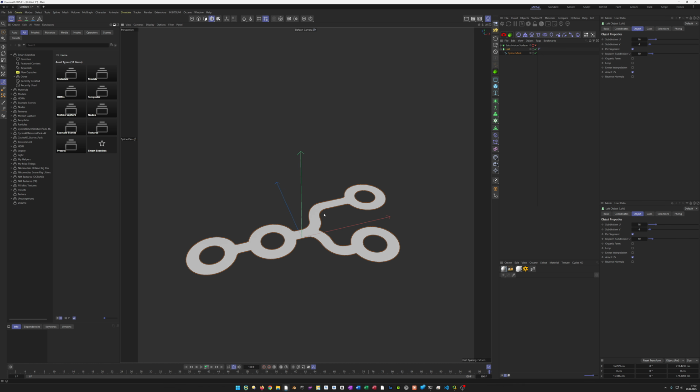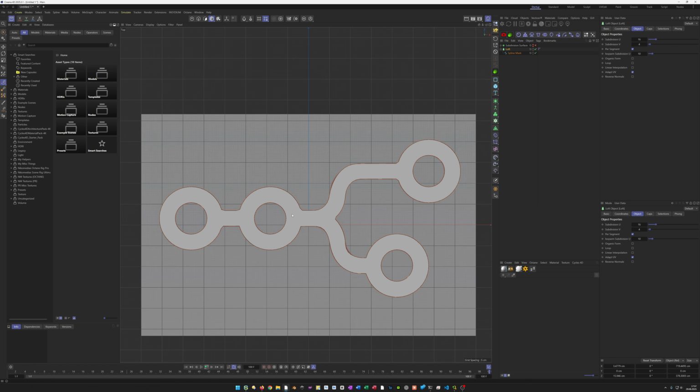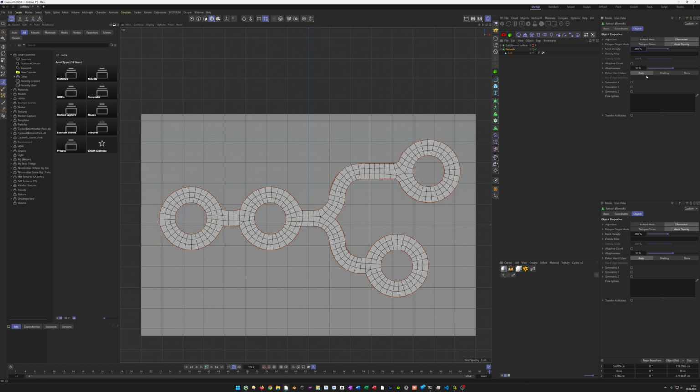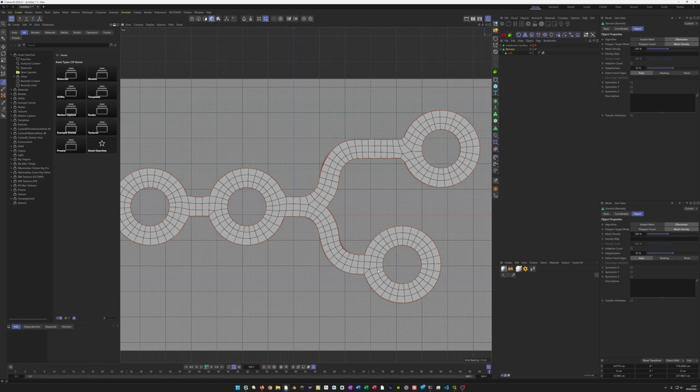The next thing I want is the same as before. I put this in a remesher. First, I go to the loft and make it editable. C on the keyboard. Don't need the whole thing here. Then we go to the remesher, select it, Alt key, remesh. We have exactly what you see. We have here triangles. But here is a triangle, but this doesn't matter because I want 200 here. And we have still a triangle here. We try to dissolve this.